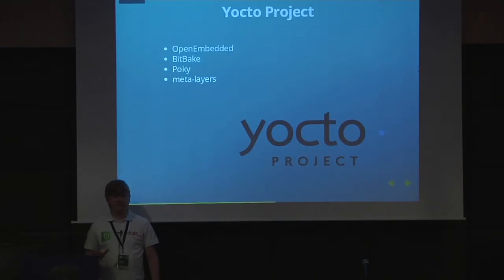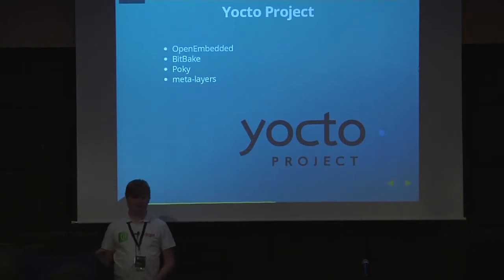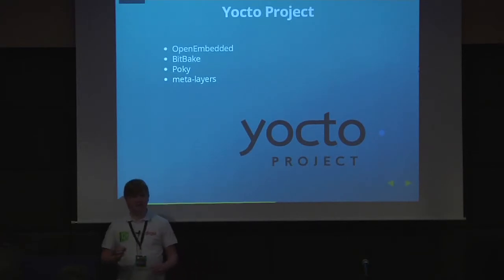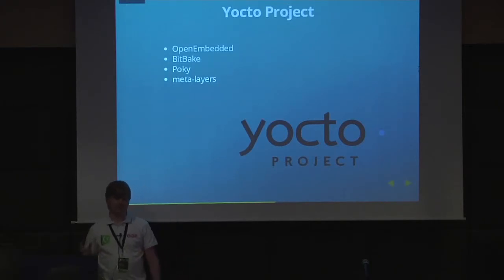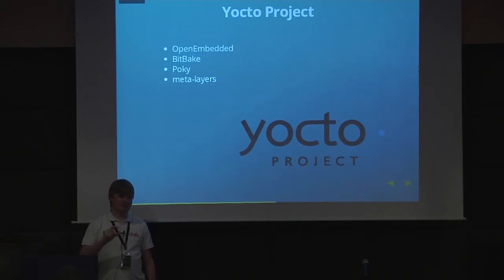So you can build a distro using individual parts. So maybe you defined a recipe that defines what a base layer system is, like what packages, libraries you need to install into your sysrooted image. And then you can take additional layers that are maybe provided by device manufacturers like Freescale and Texas Instruments, that actually are distributed as part of the BSPs that include the drivers, the kernel patches that are specific to their hardware. And then you can swap out that meta layer based on what hardware you want to actually build for.